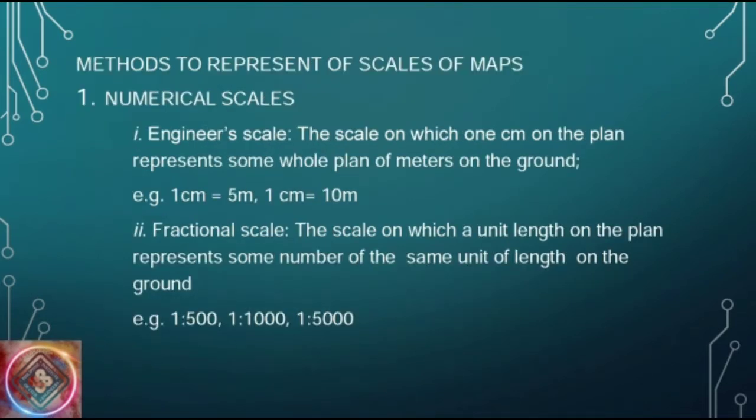Methods to represent scales of maps. 1. Numerical scales, or engineer scale. The scale on which 1 cm on the plan represents some whole number of meters on the ground. For example, 1 cm is equal to 5 meters, 1 cm is to 10 meters.